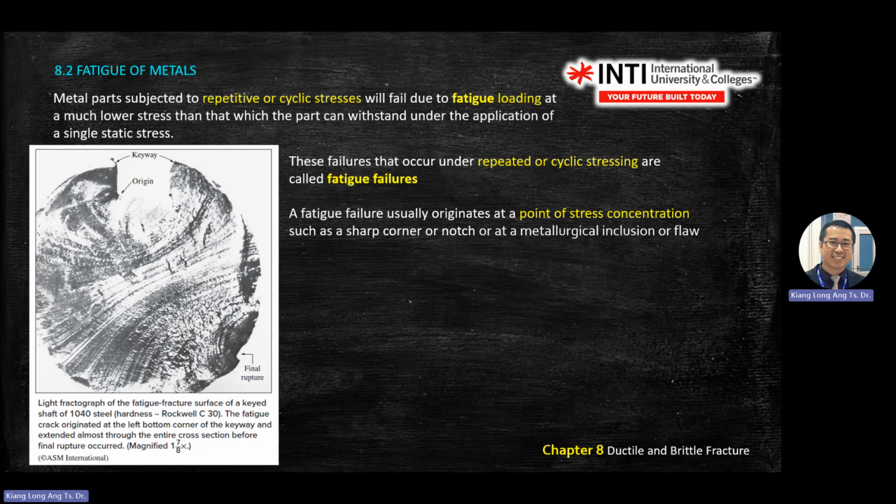Okay, so fatigue of material, sometimes you can do cyclic stress. Cyclic means you continue to load it: load, then release, load, and then release. It's called a dynamic test or cyclic test. This is also something you can observe on the surface. This presentation is called clamshell. If you go to the beach and collect clam shells, they have that shell shape. You see the lines here like a clam shell.